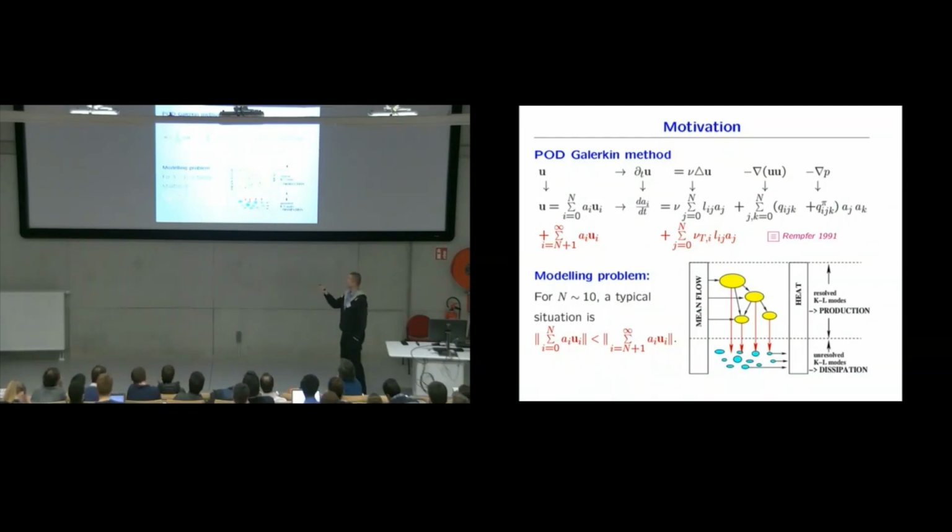So essentially, you use that the stochastic fluctuations take energy out of the resolved modes. How can you describe it? Well, you can describe it with an additional eddy viscosity here in the linear term. So the picture which is emerging is the following. We have some modes living from the mean flow. They don't dissipate anymore. They lose everything to the transfer term. You have some dissipative modes which you don't want to resolve, and this dissipation is modeled by this eddy viscosity here. So using a modal instead of a global eddy viscosity has been suggested by Dietmar Rempfer. You look skeptical? No. Okay, good.